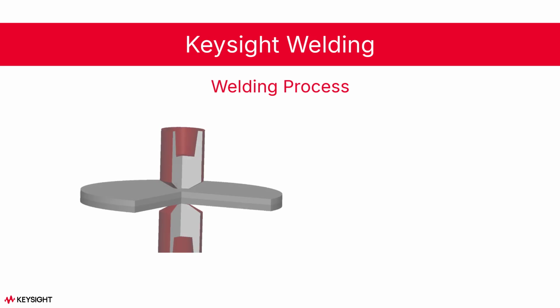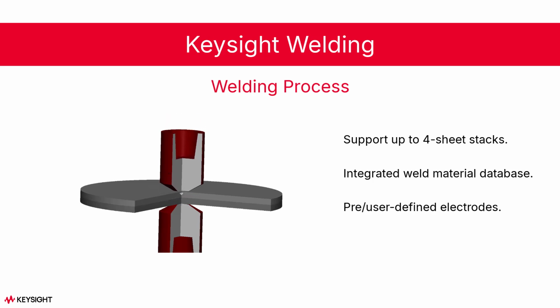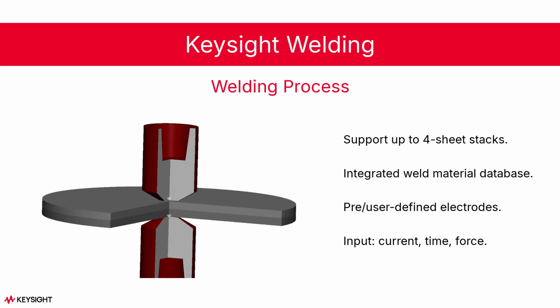First, the spot weld process itself can be validated. Stacks of up to 4 sheets can be investigated, and material parameters are retrieved from the integrated material database covering material data for both the welding process part and the rupture part. For the most commonly used metals in the automotive industry, electrodes can be selected from the internal library or defined manually if required. The input parameters for the welding simulation come directly from the real process: current, time, forces, preheating, and number of pulses.